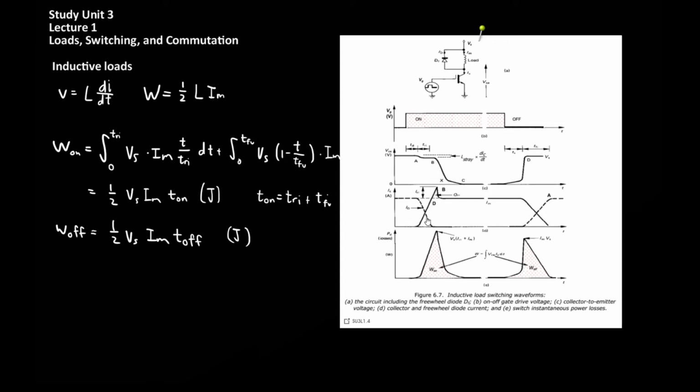An important fact to note with this type of solution is that even though this provides some form of protection from a large voltage developing over the inductor, the voltages which do develop even with protection need to be within the safe operating area of the switching device. In other words, the current which is developed here at point B still needs to be within the safe operating area for the device to prevent damage or heating.